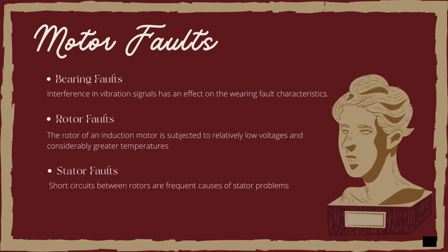Rotor faults. In comparison to the stator winding, the rotor of an induction motor is subjected to relatively low voltage and considerably greater temperatures. As a result, an open or broken bar is the most prevalent failure mode in the rotor. Stator faults. Short circuits between turns are a frequent cause of stator problems.